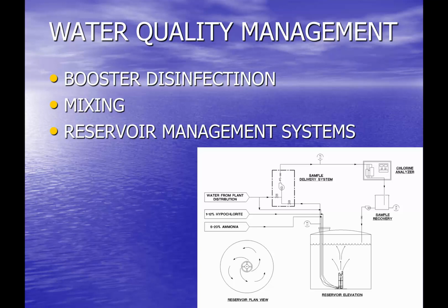So it goes a long ways towards improving water quality in the entire distribution system, as you don't allow the degradation of the water quality in the reservoir. And again, it's something that can happen pretty significantly, especially in the summer when you get that thermal stratification. Just that water age, that this does a good job of resolving, both on the disinfection residual maintenance as well as the circulation itself.